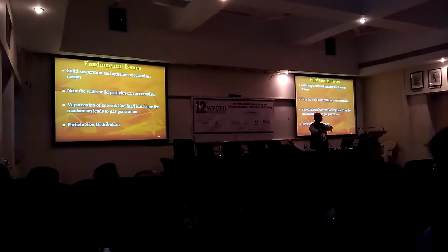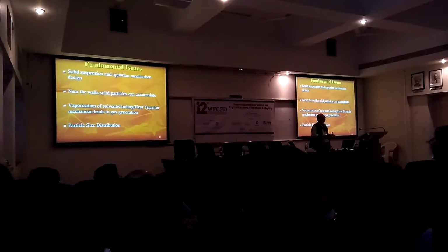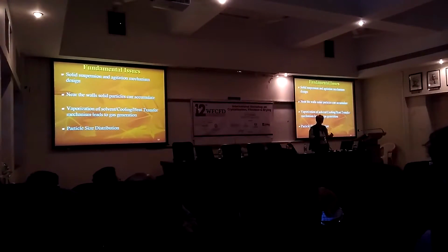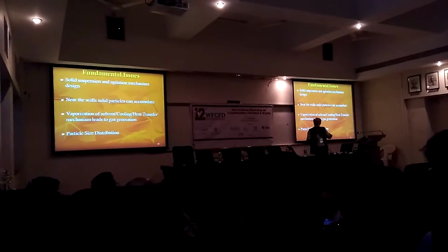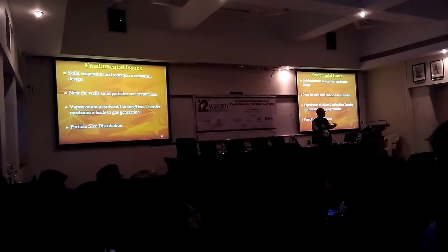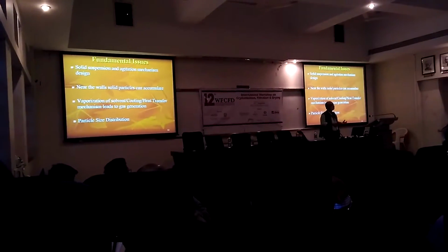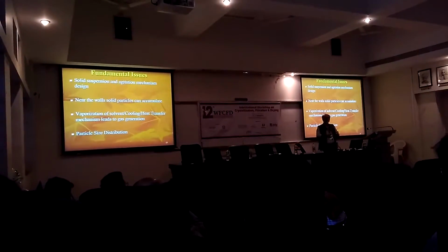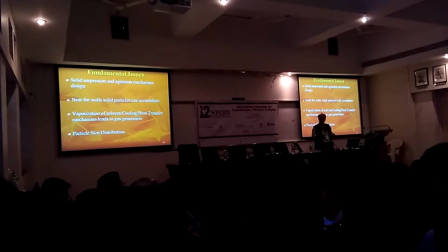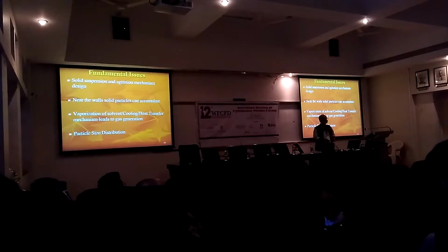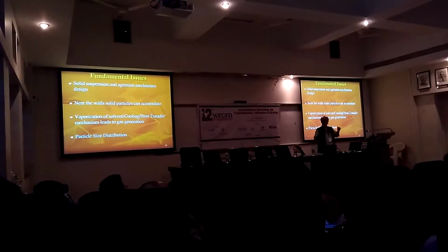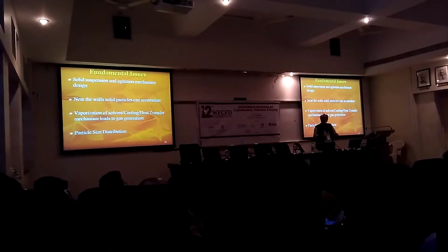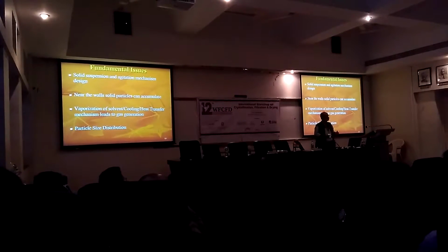So it is likely to change the entire flow pattern significantly, and if that is not taken into account, you will find if more vaporization is allowed to take place, these vapor bubbles keep occupying the solid mass, then this may result into a significant reduction in the power supplied to the system. That will reduce the velocities. That reduction in the velocities will reduce the heat transfer coefficient. That will reduce the heat transfer capability. As a result, many complications can arise.